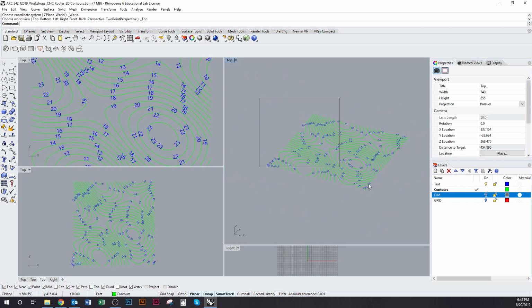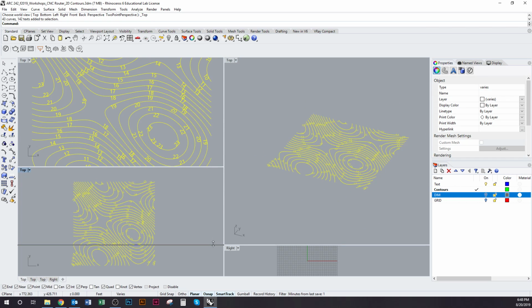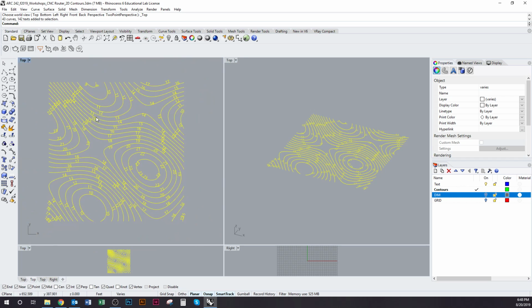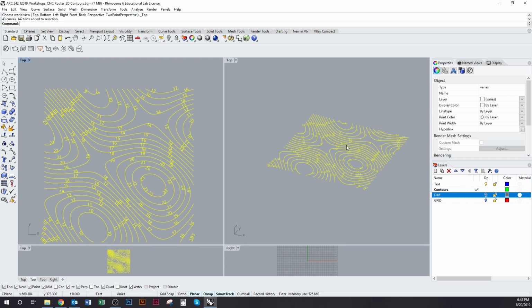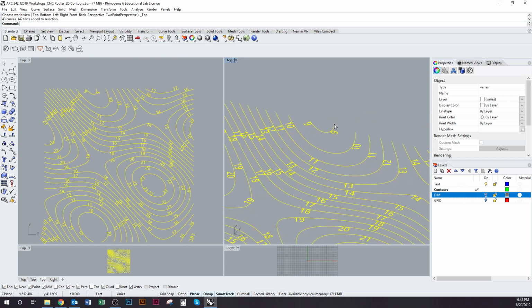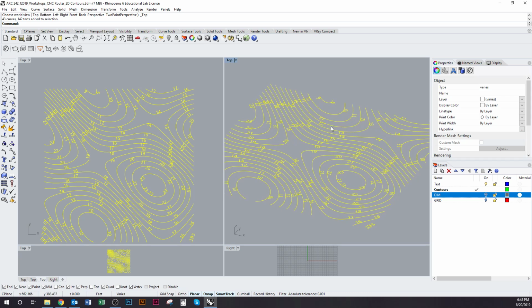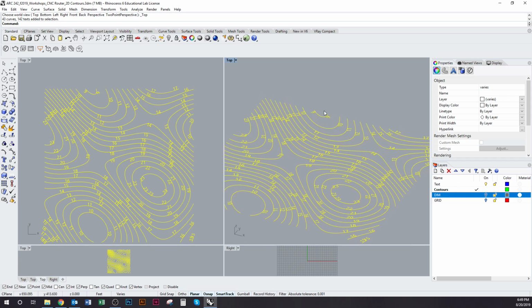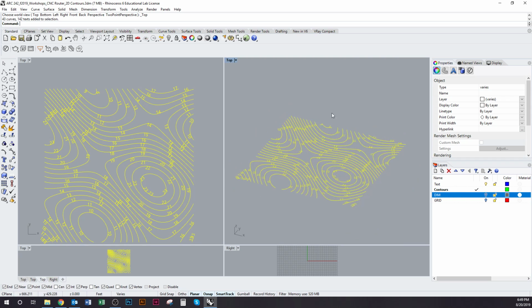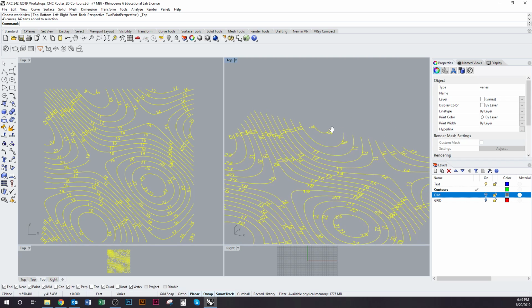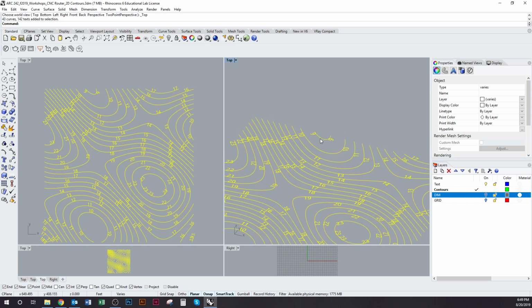Now you can see that the lowest number that you'll find on any one of these tiles is actually 9, I believe. So I think most of the tiles will have a 9, if not it'll be a 10 or an 11. But what you want to do is leave that, move the whole group of contours up to the increment of that first number.